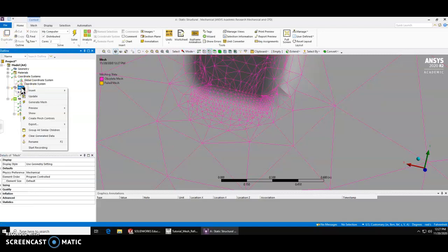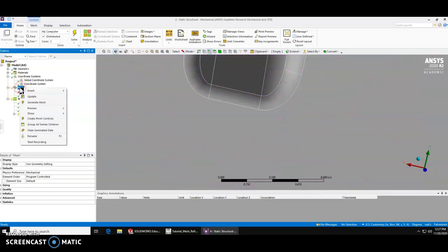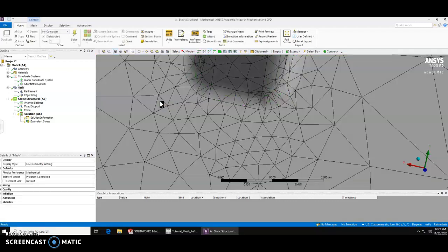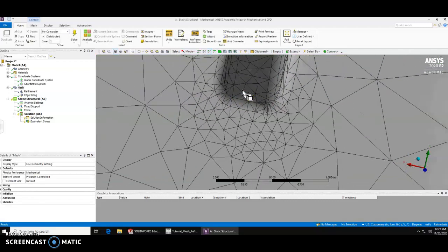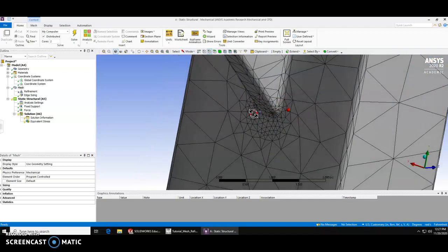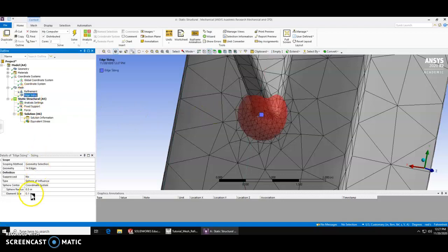Now I'm going to clear the generated data. That gets it to start afresh with that mesh. So let's generate the mesh now. It takes a little bit to look through it. Okay, so now we've got a refinement that is actually really nicely spread about that area. And you can see that that refinement is going up along the support, and you can keep messing with the size.